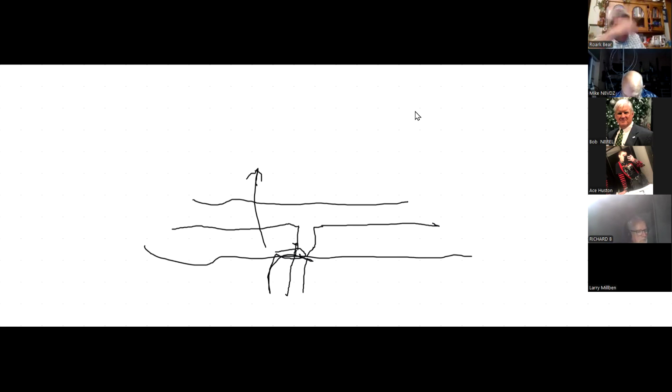And some of these things, like a tank transmitter, the tank could not put out a 64-foot long dipole for its antenna. It used a 10-foot whip or something of that sort. So the impedance of that was just horrible, very, very low. So the output circuitry for those was designed for very low impedance antennas.